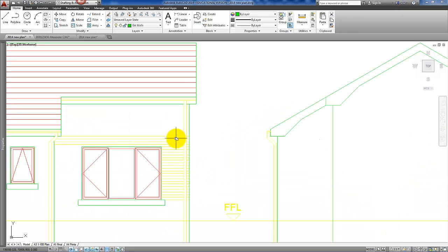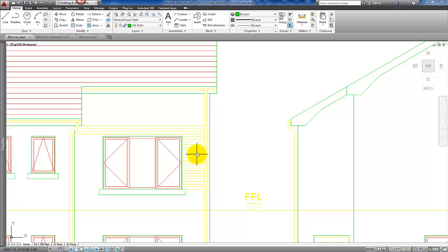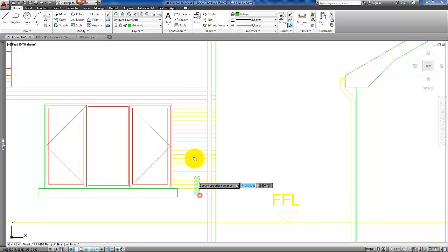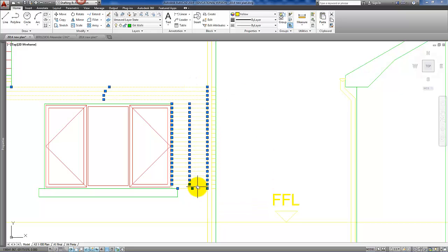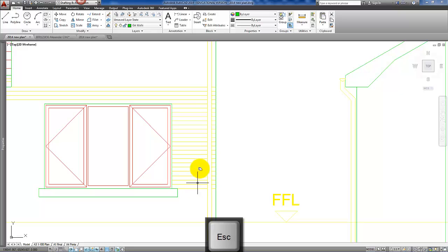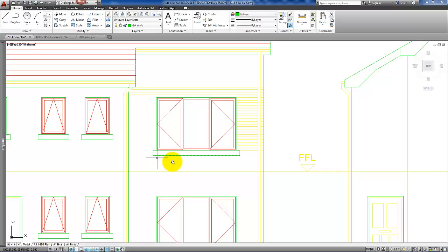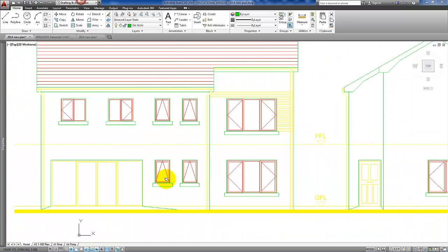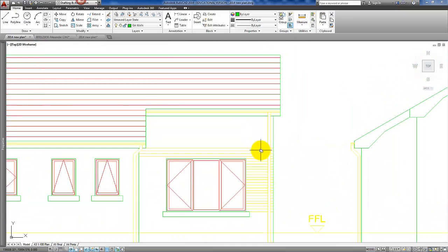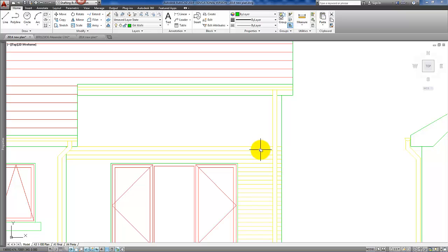The other elements then that need to be added in, if you have time at the end, would be the brickwork. And as I demonstrated in class, the lines up the brickwork there need to be at 75mm in between, and take care not to continue the lines in front of the down pipes. Take care around all the openings and below the sills, and just fill in all the gaps there that would be brickwork. As I said, the distance is 75mm. It's pretty quick with the array tool if you use that. So let's just demonstrate that.